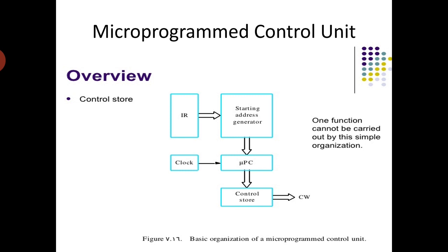But in a microprogrammed control unit, instead of generating the control signals directly, it generates them by a program similar to machine language. Depending on the code word, the processor activates the corresponding control signals.